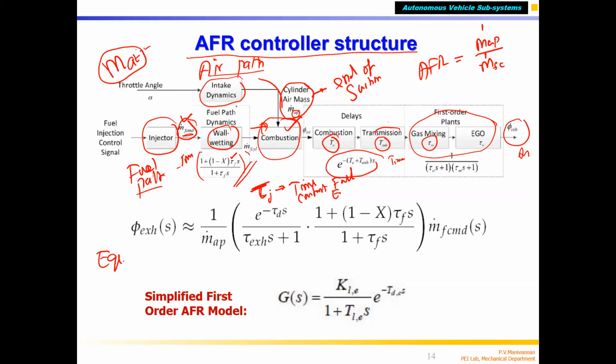So finally, this is the equation which shows the equivalence ratio. Lambda is the air fuel ratio, which is nothing but mass of the air divided by mass of the fuel. When we say air fuel is rich, it means 13:1, 12:1, 10:1. Lean means 15:1, and 14.7:1 is called stoichiometric. When you say rich, it means lesser than 14.7 is to 1, the stoichiometric air fuel ratio, which is the reference.